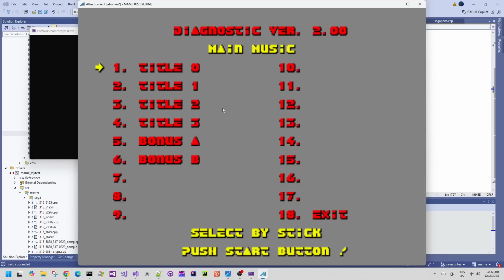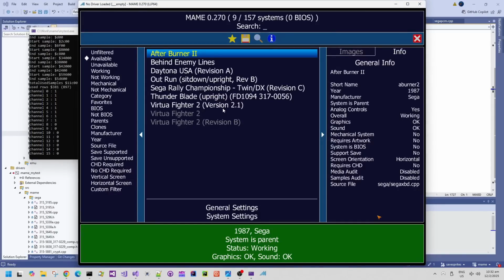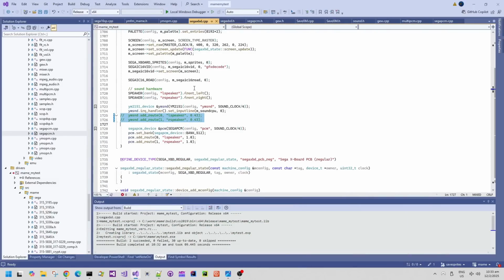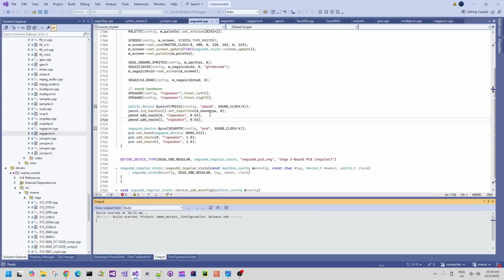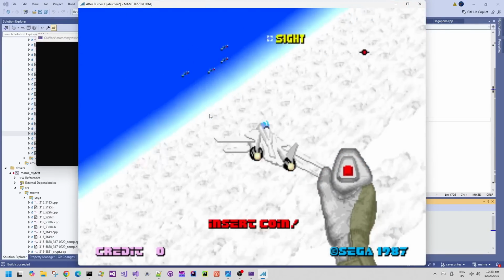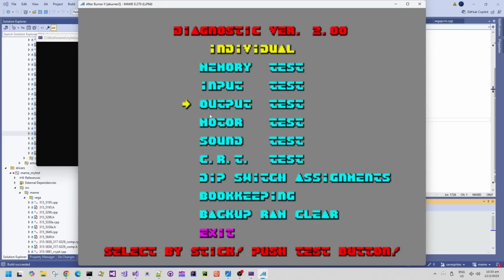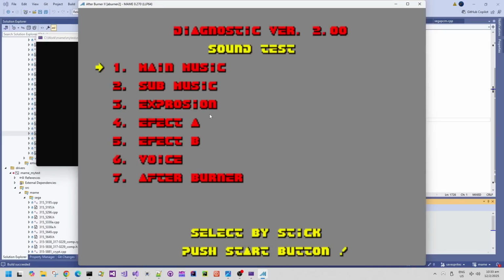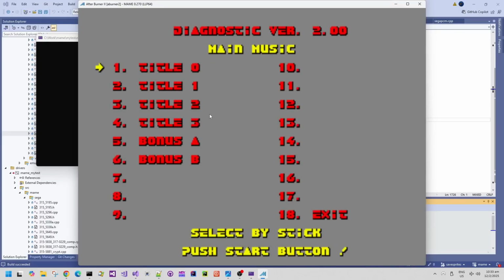So you'll notice now that the music is also missing those channels that were missing from the saved XM music file. This tells us conclusively that the YM2151 device is really important for supplying some of the music channels that are used in Afterburner. Unfortunately, the YM2151 device is different to the PCM device. The PCM is basically a sampled audio player, right? We have digital samples that go through to the audio hardware. So there's a clear difference there.